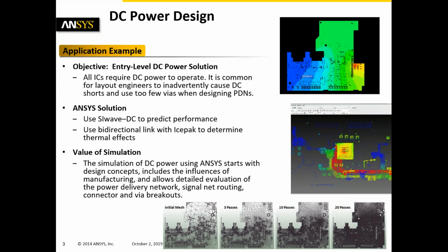The value of this simulation is that the simulation of DC power using ANSYS starts with design concepts, includes the full influences of manufacturing, and allows detailed evaluation of the power delivery network, signal net routing, the connector, and the via breakouts. So that was the content on the slide.